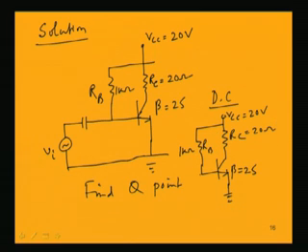The current which will be flowing is capital I capital C in the DC condition we are considering, and this current is capital I capital B, base current DC. So, in order to know this DC base current, what we have to do is that we consider the circuit and apply Kirchhoff's voltage law. So, applying KVL to the base circuit,